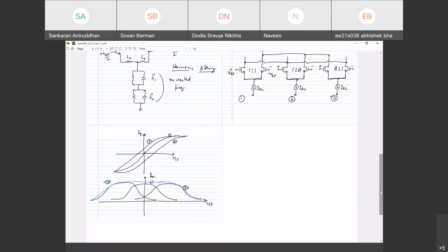It is possible to change that. So imagine you are able to change the current flowing through one of them compared to the other. Then the voltage VID at which the differential current will be zero will be positive or negative. Does that make sense? Take a differential pair.